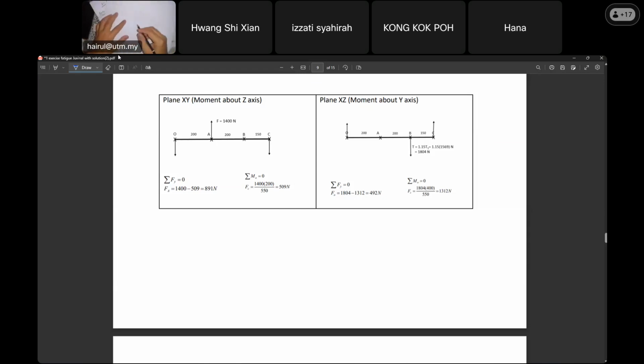Can you see? The shaft is rotating. As I told you, the shaft is rotating. And we have a pulley, D is the element, B is here. The shaft is rotating, and at the top it faces tension, at the bottom it goes to compression. Up tension, down compression. Because the shaft is rotating, the element is rotating.